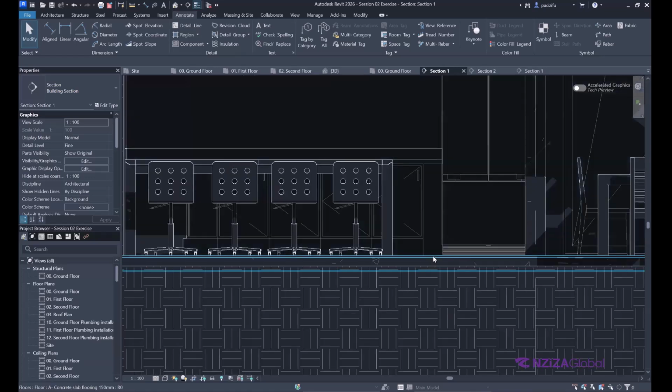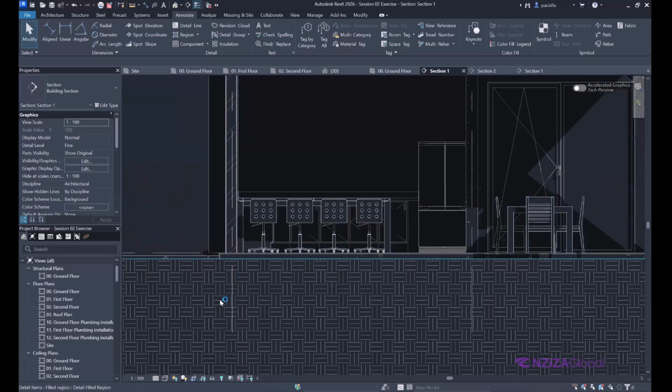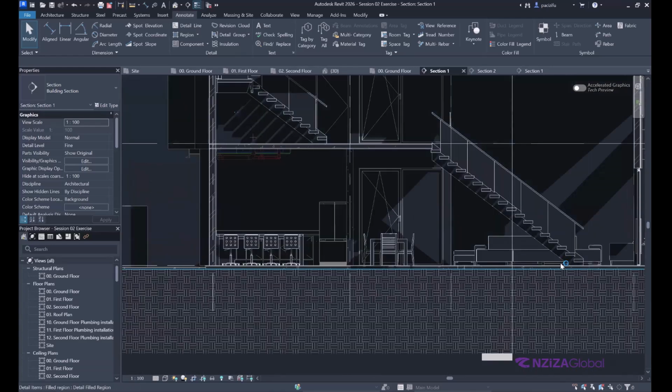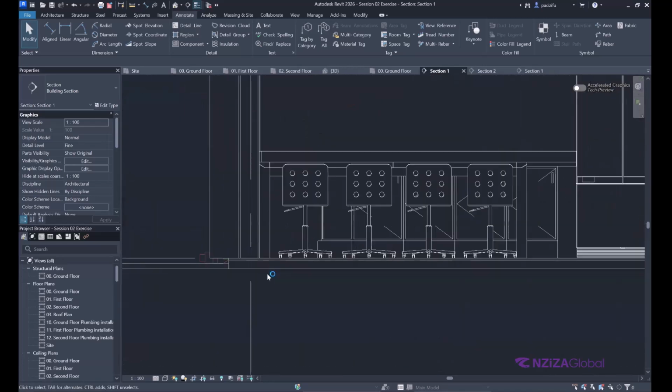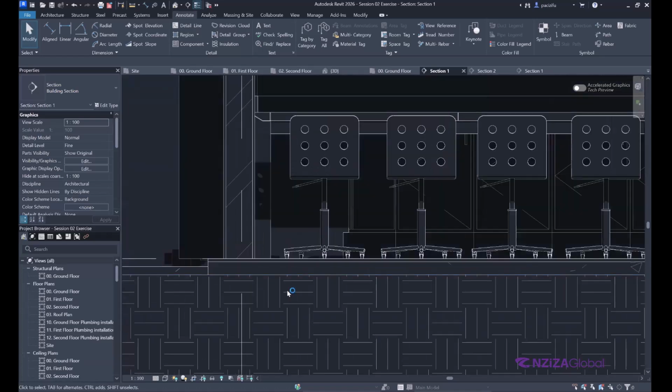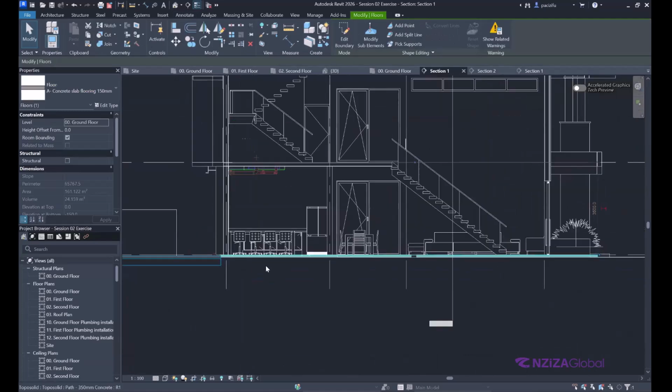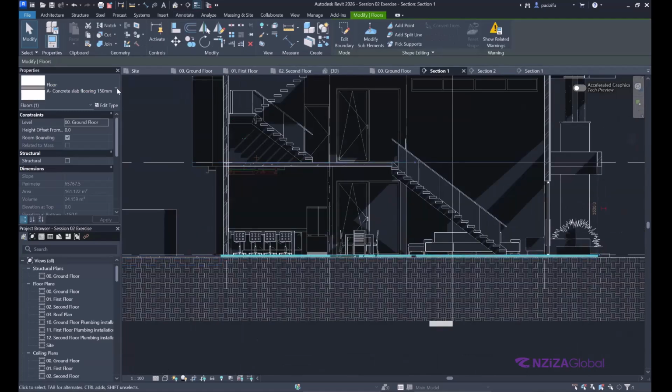Then we select it and add some layers for compaction, hardcore, and DPM or DPC. Then show, then edit this fill, then show all of the layers under this building. You just select the slab, which is down here.